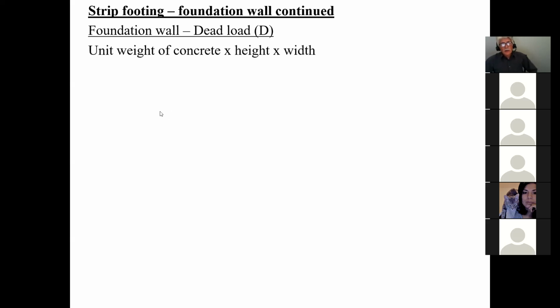Basically, when it comes to residential construction foundation walls, the most typical width of a foundation wall is 8 inches if the outside cladding is siding. If you have masonry, it should be 10 inches.